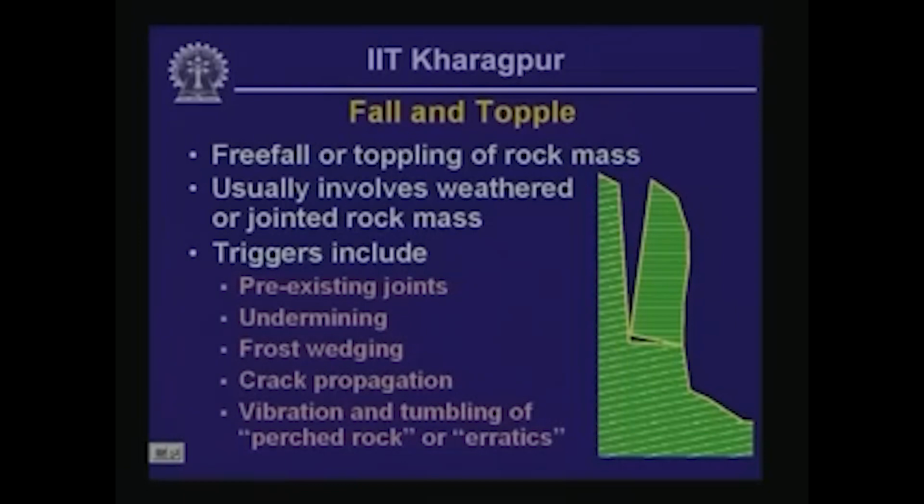Then we have got this particular section. This particular cartoon illustrates the process of toppling. What has happened here is a cracking of bedrock near the top of the slope, as is seen here, and what could happen is water could enter into the cracks there, and that water pressure could destabilize the rock at the top corner of the slope in this particular case.